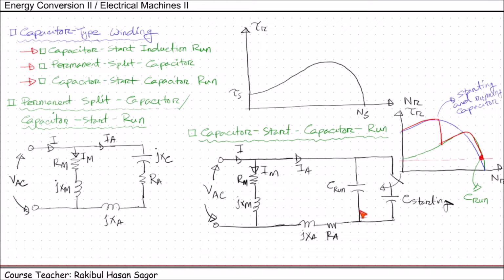The permanent capacitor is just large enough to balance the current at normal motor loads. So the motor again operates efficiently with a high torque and power factor. Generally, the permanent capacitor in such a motor is typically about 10 to 20% of the size of the starting capacitor.